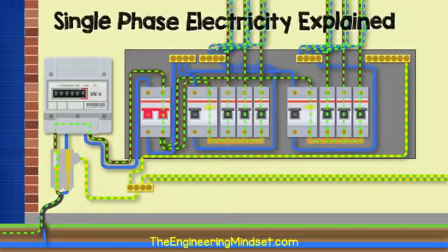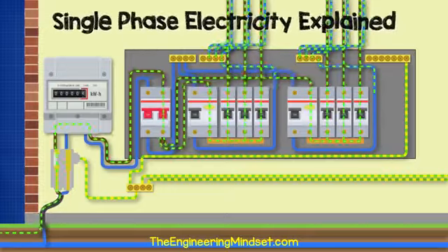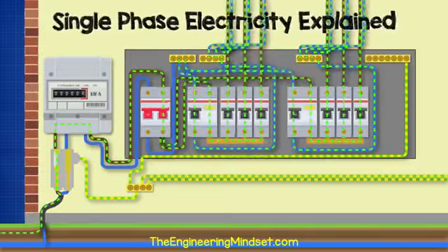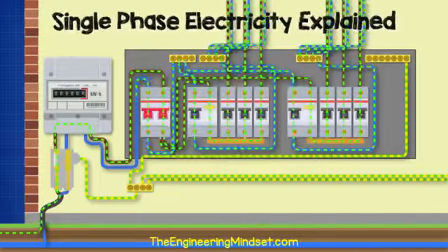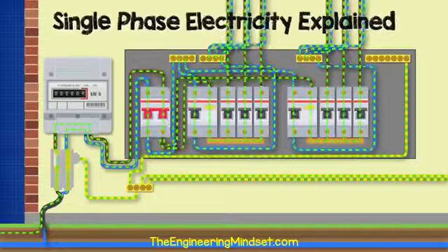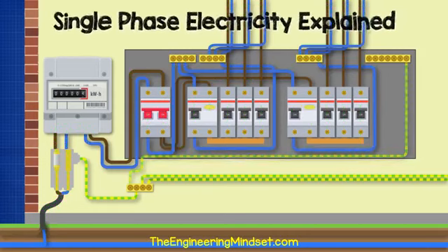The electricity can then come back via the neutral lines and into the neutral blocks. It then flows through the RCD and back into the main block. From there back into the main switch and then the electricity meter. It will then pass through the service head and the fuse and back into the neutral line of the main distribution cables.